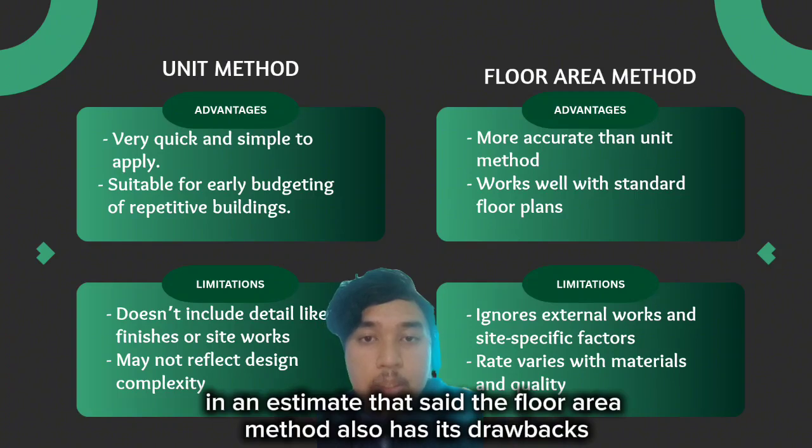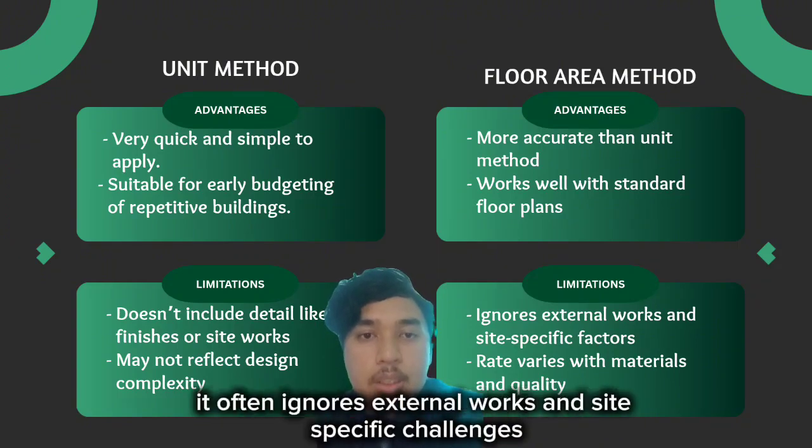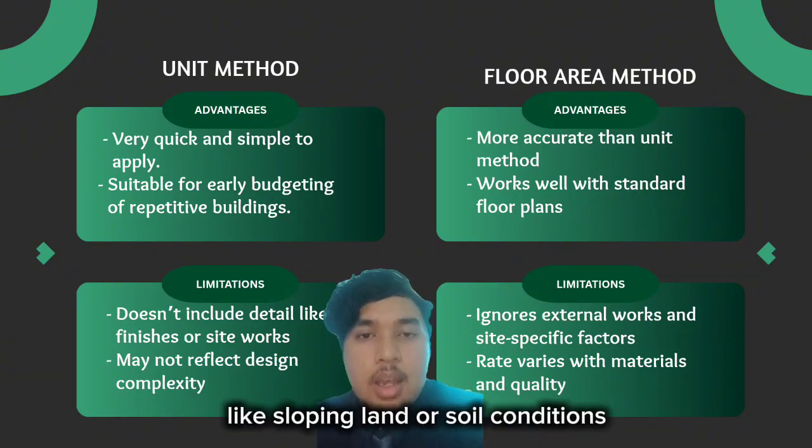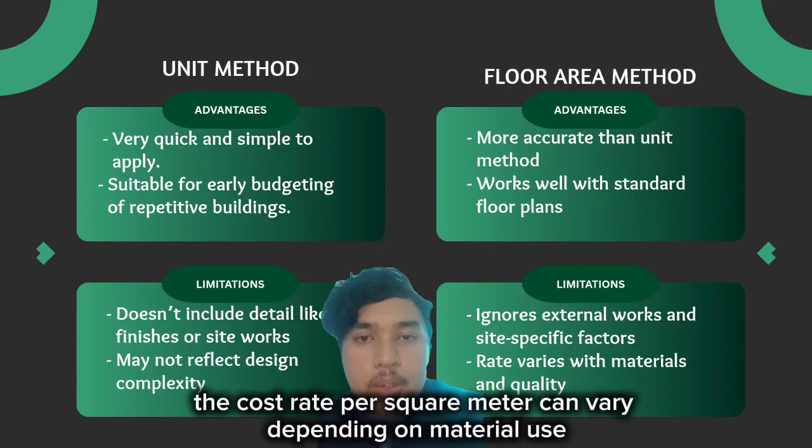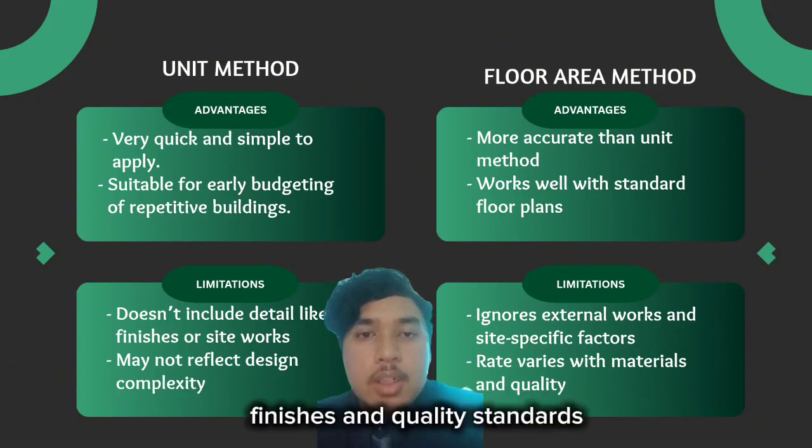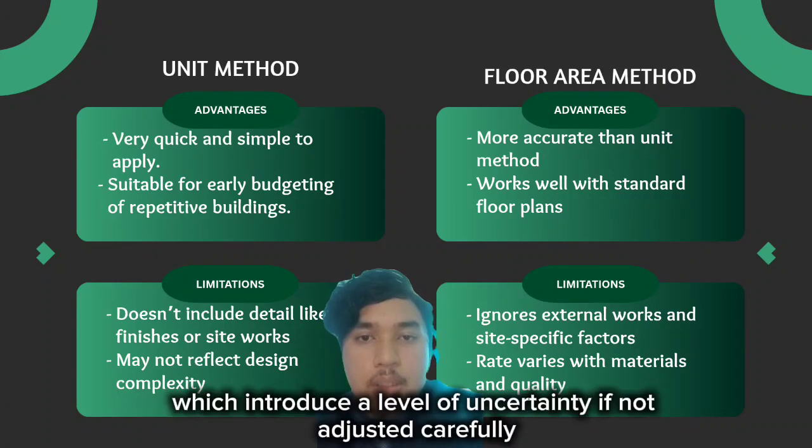That said, the floor area method also has its drawbacks. It often ignores external works and site-specific challenges like sloping land or soil conditions. Additionally, the cost rate per square meter can vary depending on material use, finishes, and quality standards, which introduces a level of uncertainty if not adjusted carefully.